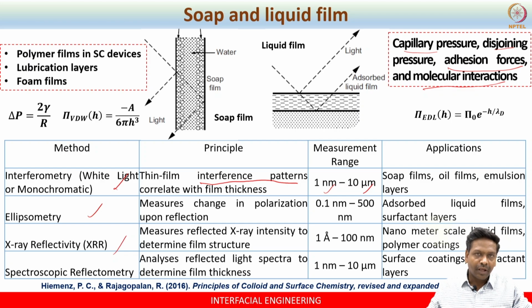By measuring these two parameters at the critical salt concentration, we can substitute these values into the equation that we derived in the previous lecture, that is the electrostatic force due to electrical double layer interaction. If you plug in these values, we get the electrostatic repulsive force itself. Since we know the electrostatic repulsive force, and we also know that coagulation occurs when the surfaces overcome the electrostatic repulsive force, right.